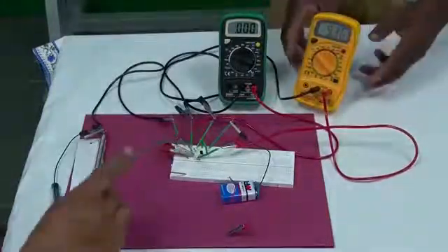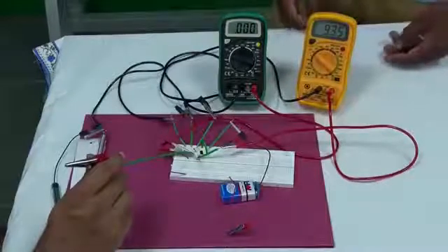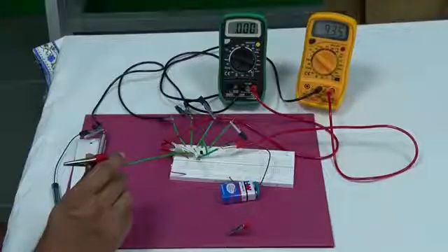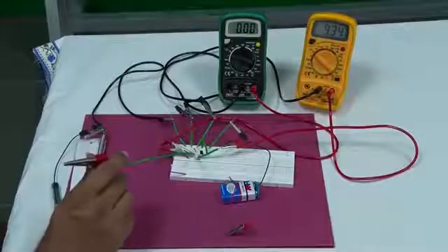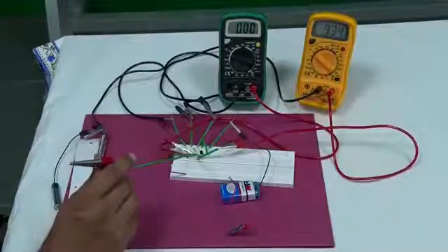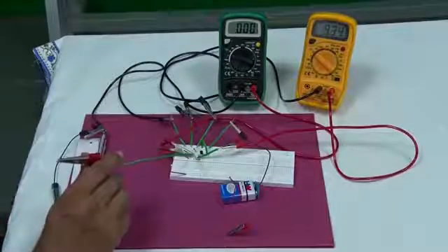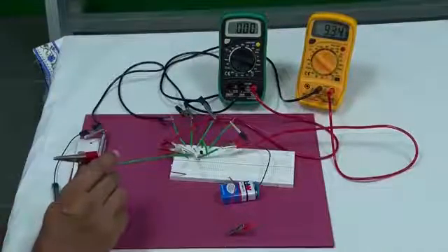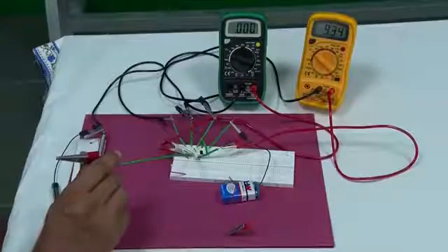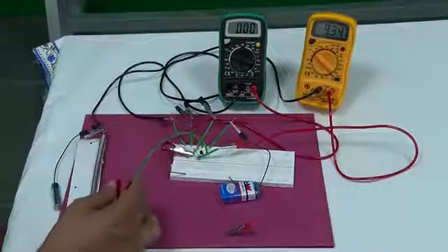So, I have not given any bias voltage, but you can see the output is 9.35 volt. Okay. That is natural, there is no bias voltage. So, there is no base current, there is no collector current, and therefore, whatever is the voltage of the positive battery, that appears at that VO point, and that is 9.34. So, now let us start giving some bias.